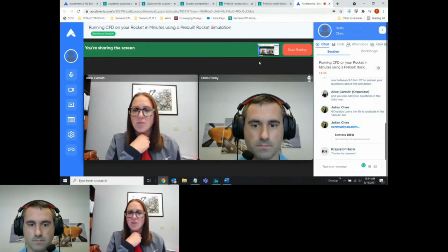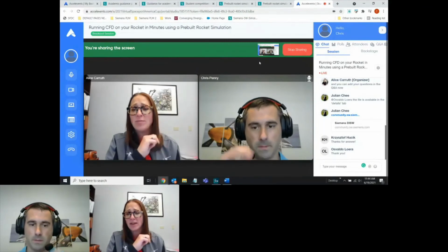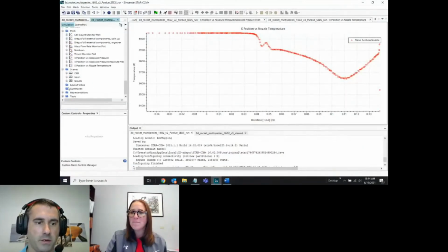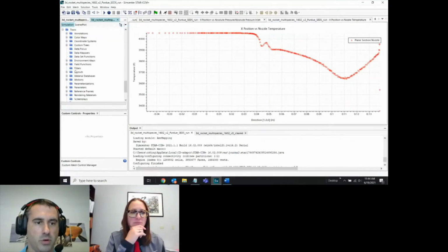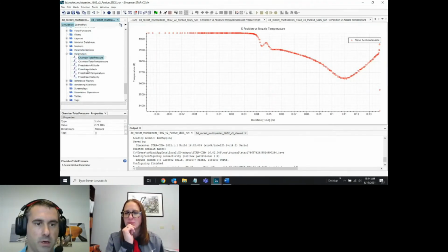The next question comes from Julian Chi. It says, I'm not too proficient in CFD software, but is there a way to iterate this through a range of free stream Mach? Yes. So all you need to do is come back down here to tools and parameters, like I showed before. If you have tools and then parameters, you can just come down here and change the free stream Mach.